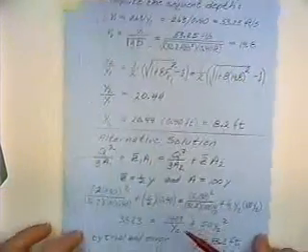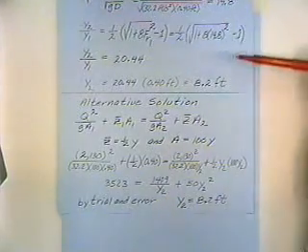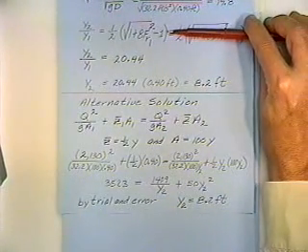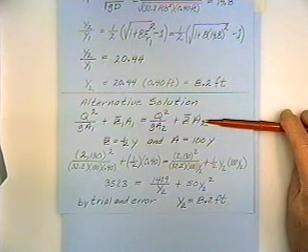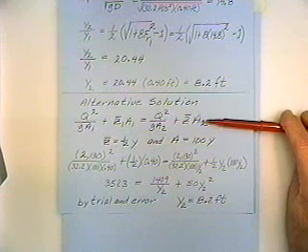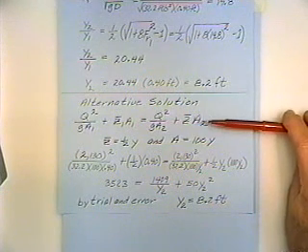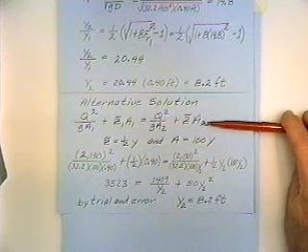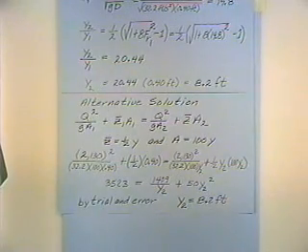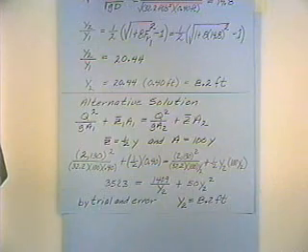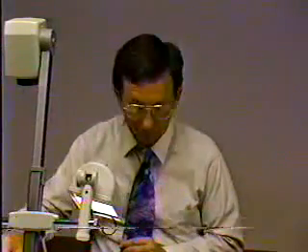Now, if we wanted to, an alternative way of doing that: this equation is valid only for rectangular channels. This equation is valid for any type of geometry, including a rectangular channel. So here we've just used the basic conservation of momentum equation, plugged in the numbers to get the same answer again. So the equations do give identically the same answer.